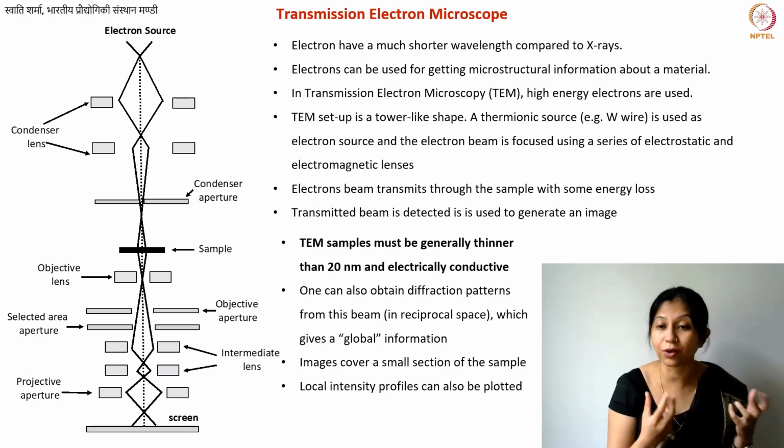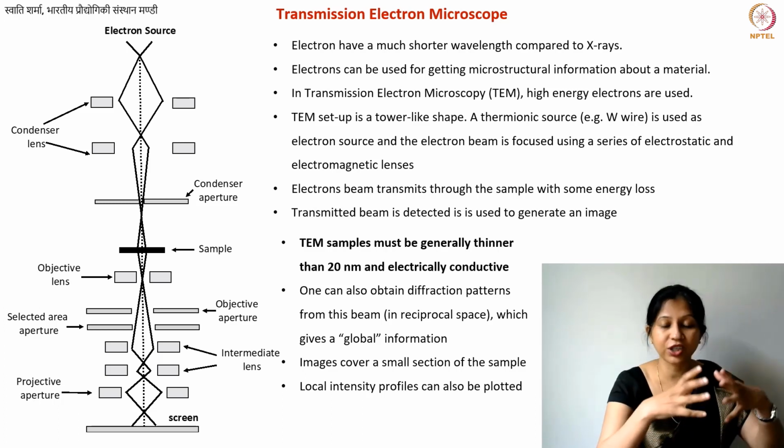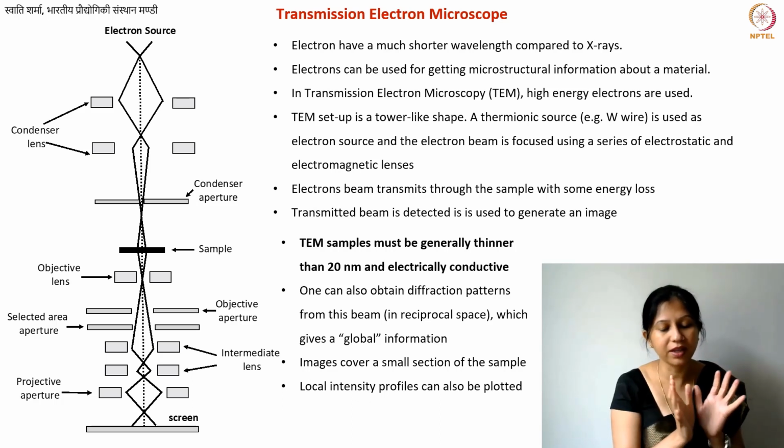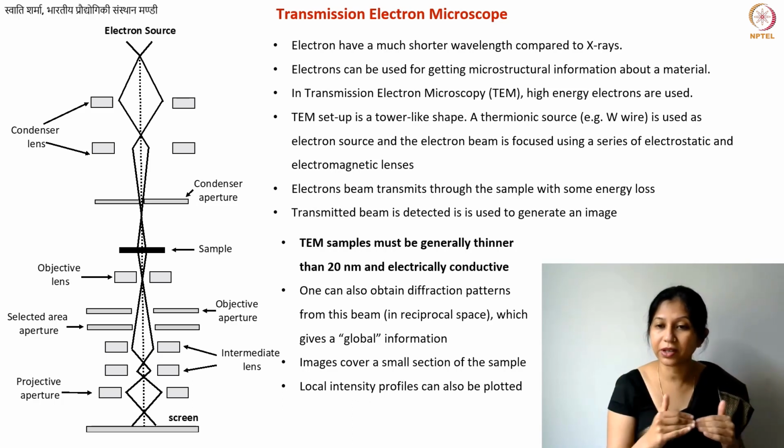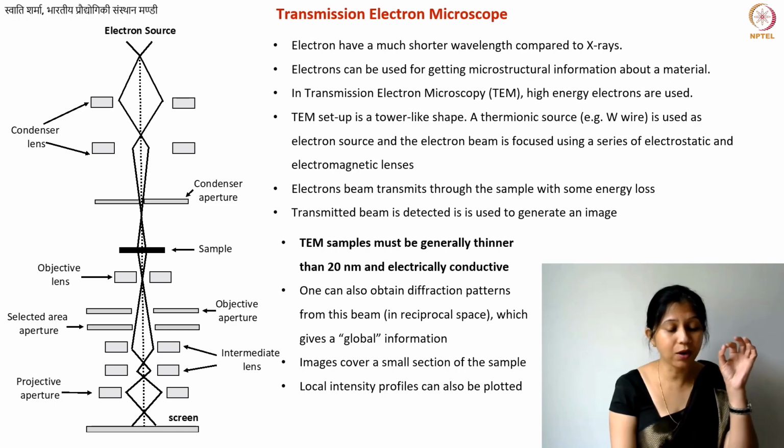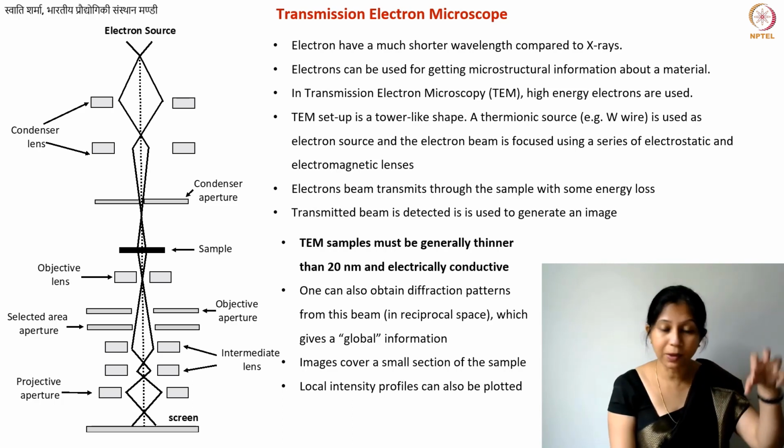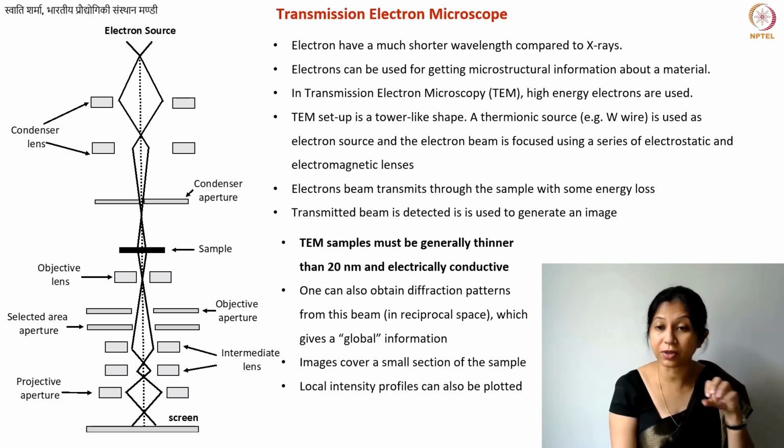Certain microstructure can also come from, let's say, some non-carbon atoms in your material. They may change how your 6-membered rings are organized. Because of defects, you can have different strains in the sample. So if you're sampling only one part of your material, you may end up getting misleading information. So you often need to perform the microscopy at different positions on your sample, on your specimen.